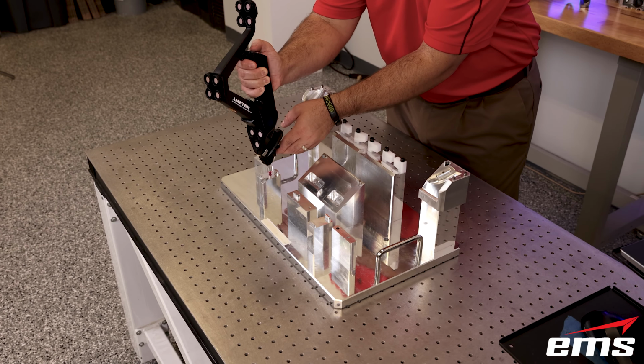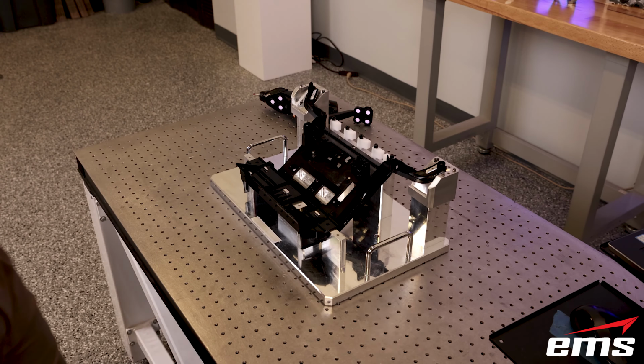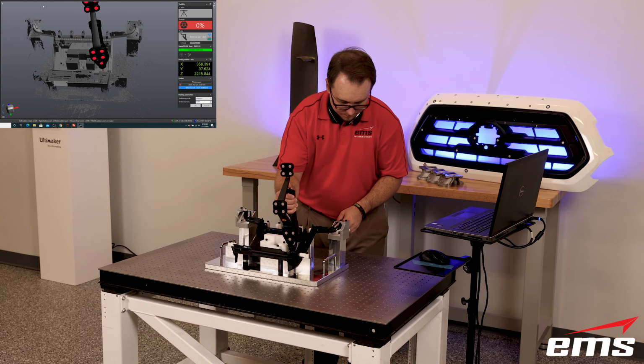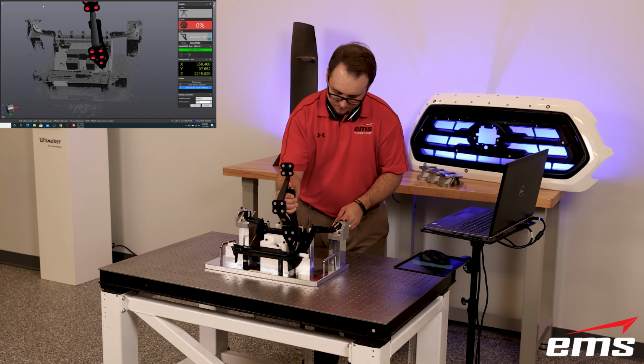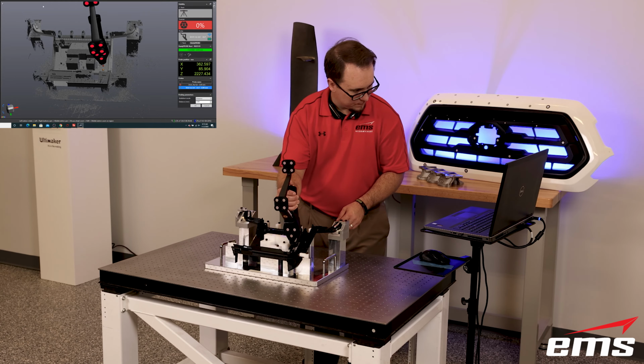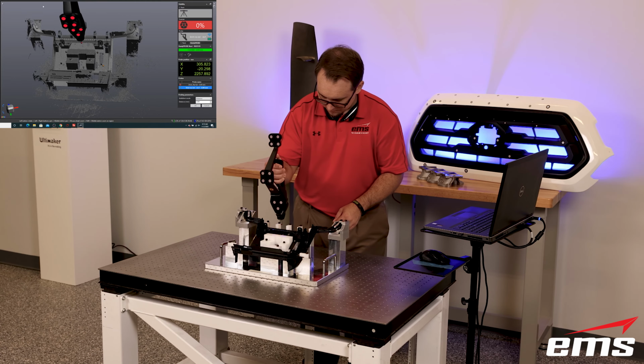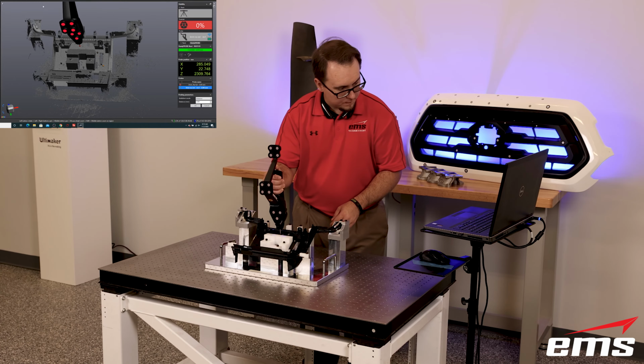Once the fixture is validated, we can now place the part in the fixture, clamp it down, and that's going to hold that part in the correct position. So this is a case where a fixture would absolutely be required to hold the part in the correct assembled position in the vehicle. And then from here, we're going to use either probing or 3D scanning to inspect the part, and it can be a combination of both.